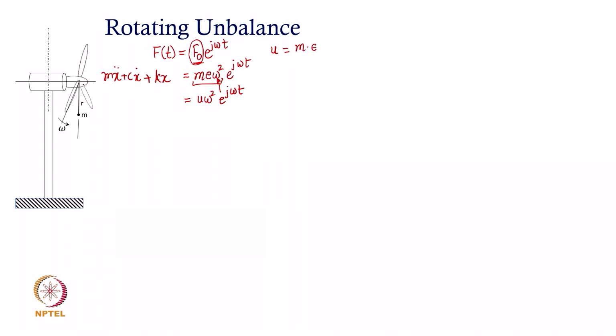So, for example, this would be epsilon, the position of the unbalanced mass m from the axis of rotation. This m multiplied by epsilon, that product itself is the unbalance, and there is a practical reason why it is usually clubbed together as a product and called unbalance. So, the unbalance has a unit of kg meter as the product of mass and the eccentricity epsilon.